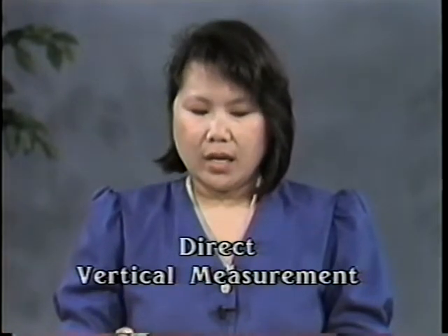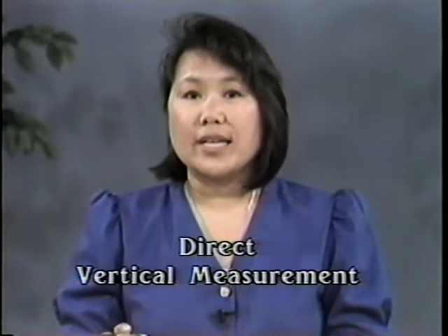Now, Carol will introduce the 3 methods of vertical measurement leveling we'll be covering. The 3 leveling methods we will be covering are direct vertical measurement leveling, trigonometric leveling, and differential leveling. The first topic, direct vertical measurement leveling, is, according to the Caltrans Manual, Chapter 5, the direct reading of elevations or vertical distances. Values are not mathematically manipulated except to apply corrections and adjustments.